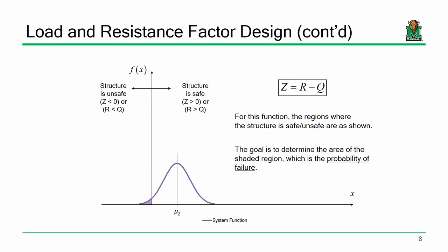You take steel design, you take concrete design, take pre-stressed, where you focus in the building side, and you've probably seen things like 1.2 times the dead or 1.6 times the live. You've probably seen that before, am I correct? Okay. If you've seen that before, what that is when we use 1.2 times the dead and 1.6 times the live, those numbers come from trying to keep this probability of failure uniform. I mean, why is the live load number larger? Why do we use 1.6 for the live loads and 1.2 for the dead loads?